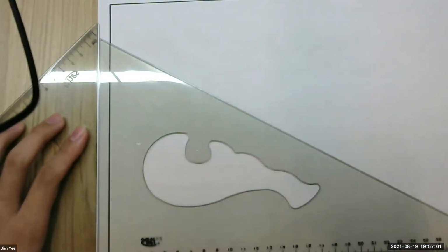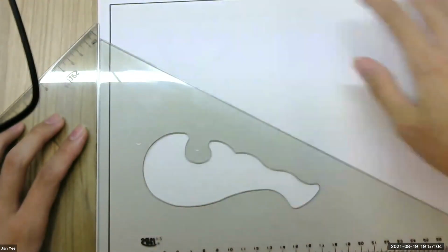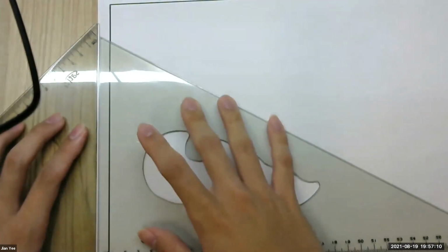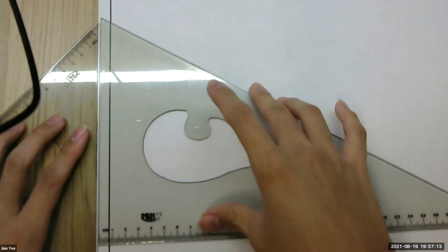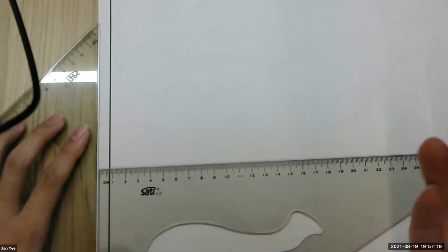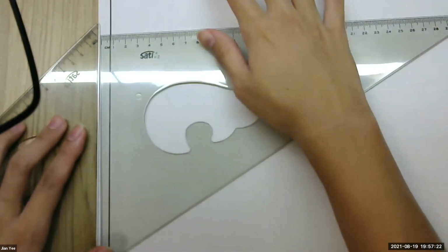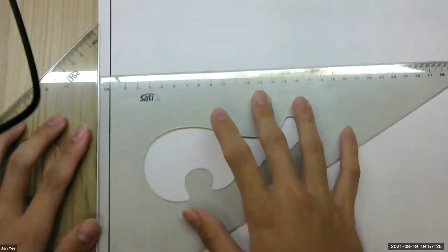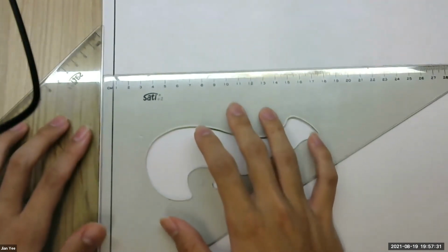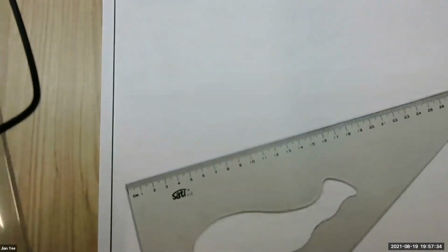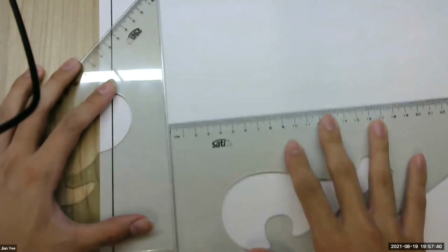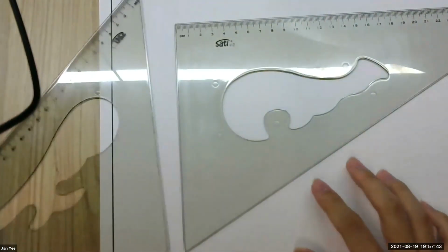And if you can, bring some tape to tape down your paper, because if not, it'll keep moving around. Some tutors I know provide tape, but some tutors don't. So if you want, just bring tape. It'll save your sanity. You can bring tape into the exam also. They won't stop you. So your paper doesn't move around while you draw. So this is how you draw horizontal lines. Don't do it any other way, because it just looks very stupid when someone's trying to draw, and then their whole thing shifts as they try to move their set square up. Don't be that guy.